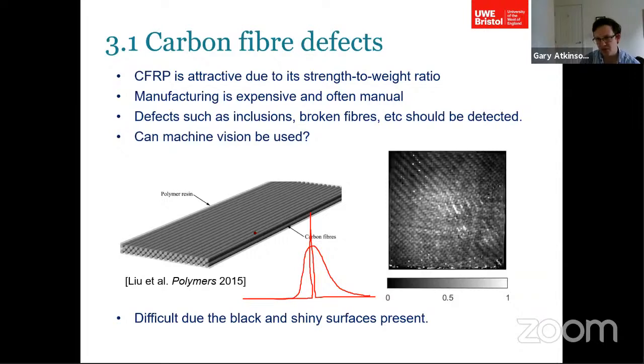For example, if the lighting is not uniform, that might cause a bit of a skew, a bit like I've inadvertently included here, actually. So what we've been doing is putting the fibers under a dome illuminator, so we can be certain that the surface is illuminated from all possible directions. So that's the optimum case. Having said that, you don't have to do that. It's just the optimum case. So it's affected a little bit by resolution, a little bit by the quality of the material, and a little bit by the illumination. But you can normally measure to about a degree precision.